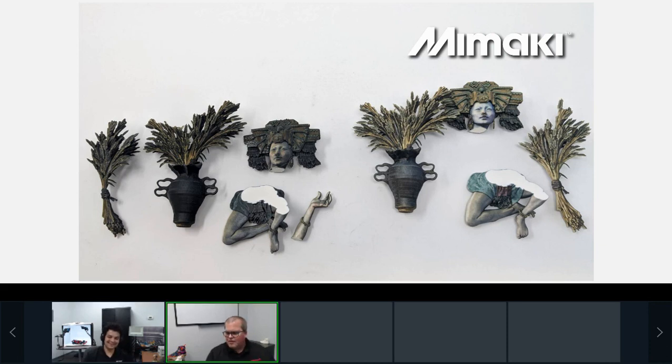So we've got another question on color, which is, does the machine color drift over time and require recalibration, or does the color profile only need to be calibrated once? I think we would both agree that while it's a 3D printer, it's still an inkjet printer, right? Inkjet printing, regardless of 2D or 3D, depends a lot on the environmental conditions. The profile for these machines is made under a specific condition, and as long as the machine stays within that condition, you should get consistent color.